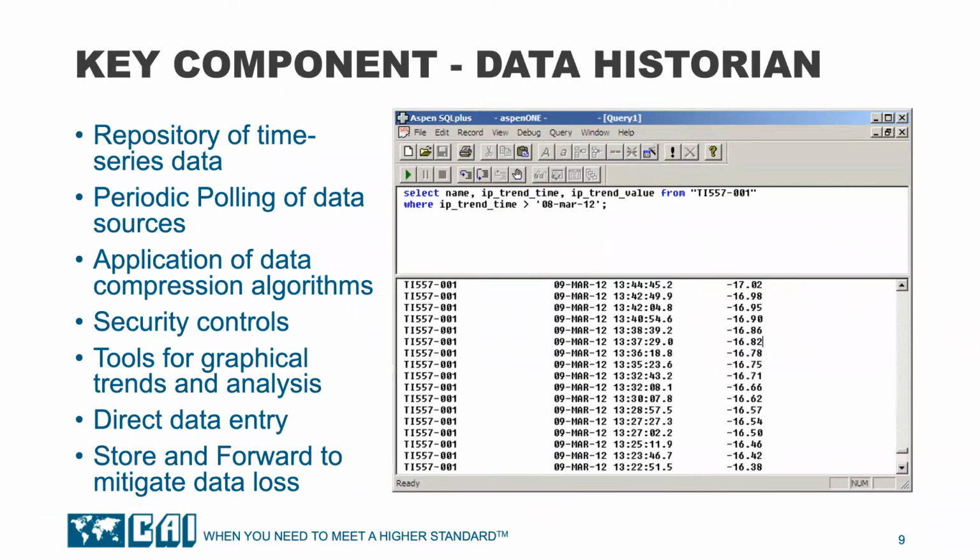Here are some aspects of the data historian which make it the perfect cornerstone for our data infrastructure. A data historian timestamps the data values that it collects. Historian data is often referred to as time series data. Typically, a data historian will only store tag value, time, and tag quality. Tag quality is a qualitative good, bad status for each tag value collected.